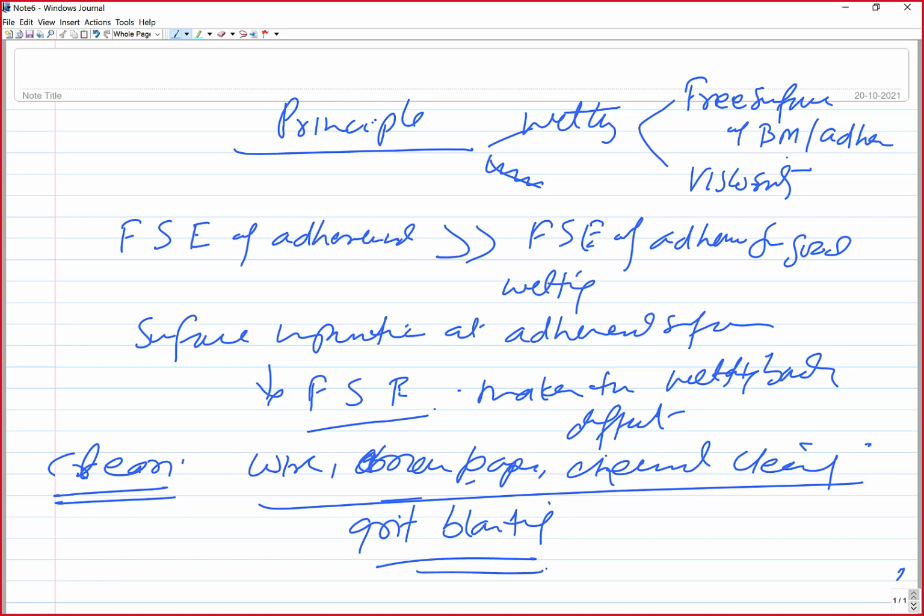Okay, and when the viscosity of the adhesive is low, it will allow easy spreading between the adherent surfaces, and if it spreads properly, then the bonded regions will be high, and the possibility of entrapment of the gases and voids will be very limited.